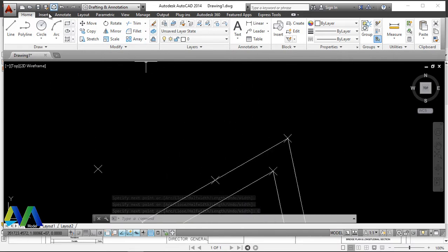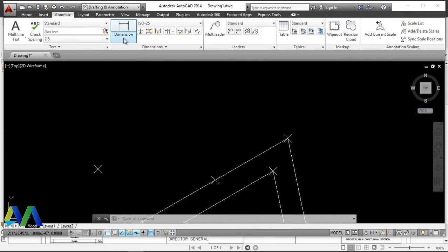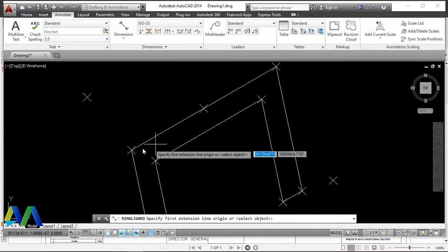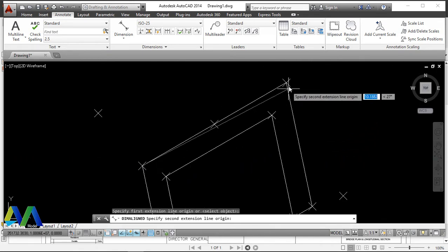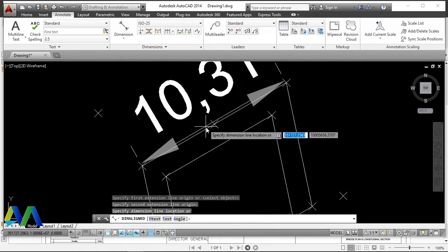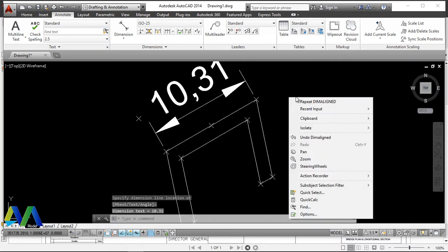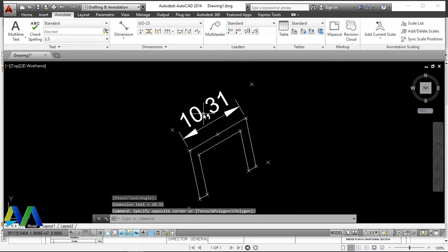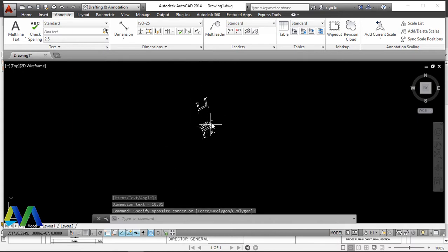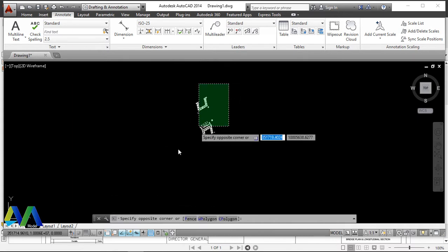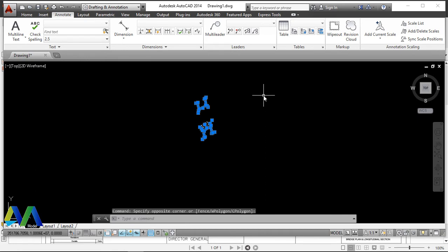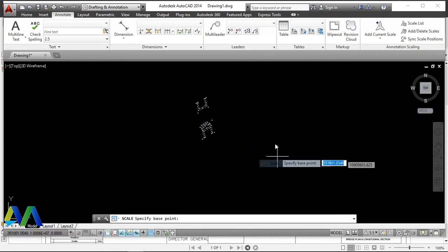Now if you come here and try to measure, if you snap on that spot and run all the way to that spot, you'll be able to see it's actually in meters. Now we want to convert this to millimeters. It will force us to downscale it by 1,000, just convert it to millimeter, a manageable size. After highlighting all these, right click and come to scale. Then on the command line, just click there and type 1000.